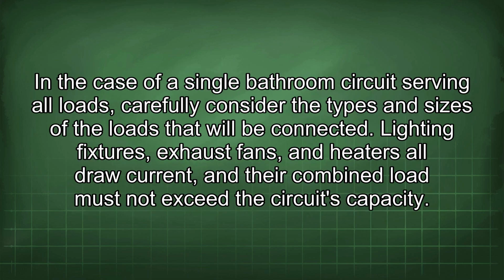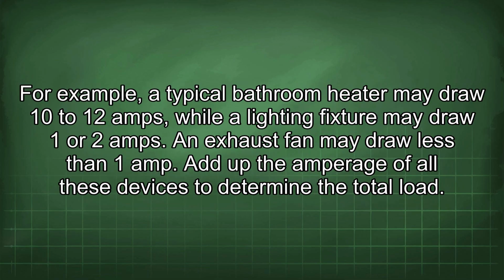In the case of a single bathroom circuit serving all loads, carefully consider the types and sizes of the loads that will be connected. Lighting fixtures, exhaust fans, and heaters all draw current, and their combined load must not exceed the circuit's capacity. For example, a typical bathroom heater may draw 10 to 12 amps, while a lighting fixture may draw 1 or 2 amps. An exhaust fan may draw less than 1 amp. Add up the amperage of all these devices to determine the total load.